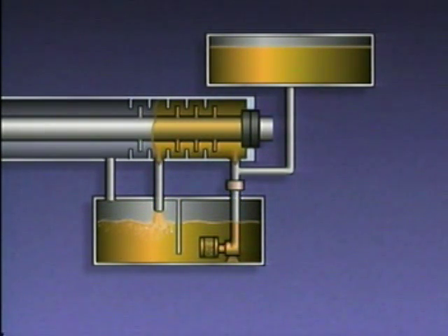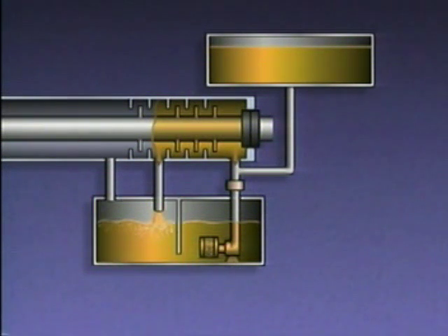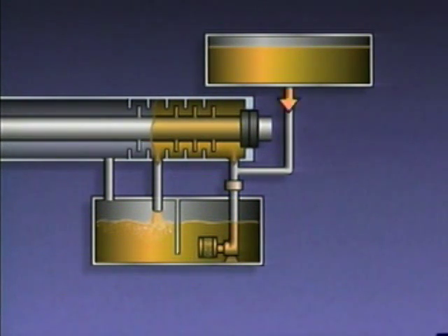As the oil comes in contact with the gas in the compressor, some of the gas is entrained in, or carried along with, the oil. The gas separates from the oil in one of the compartments of the oil reservoir. The gas rises up through the oil and returns to the compressor through a gas return line. The oil flows to the oil pump and is then returned to the seal.